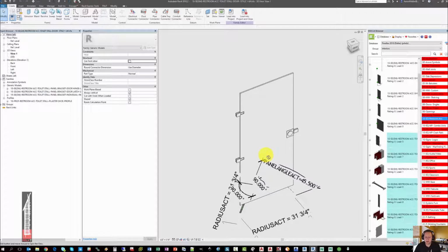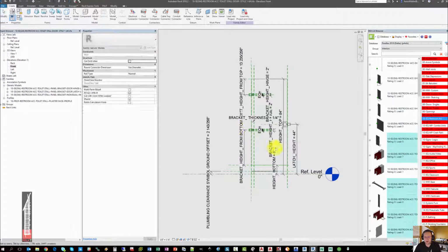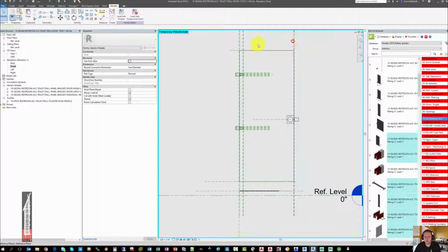You'll notice that there aren't a tremendous amount of parameters inside these components. There don't need to be since they're all nested. So if you were to simply hide the dimensions and work in between the reference planes, you could put whatever louvers or decorations on this device that you wanted, and then load in alternate styles.